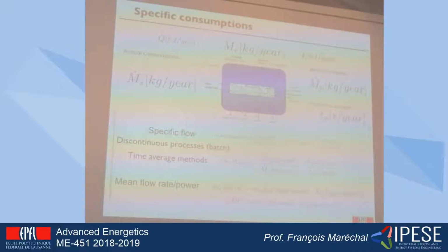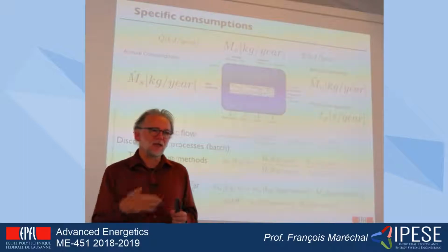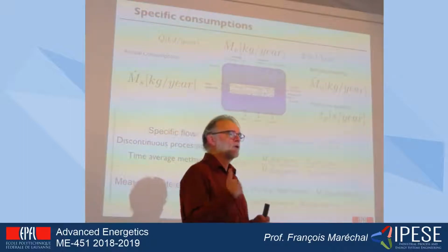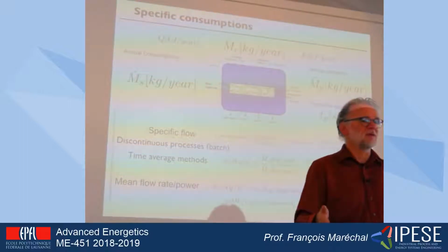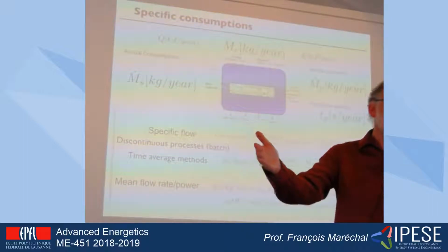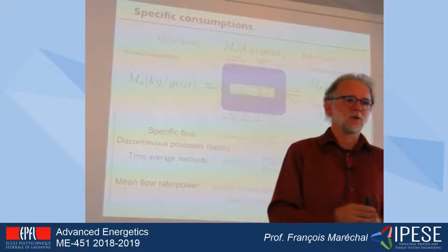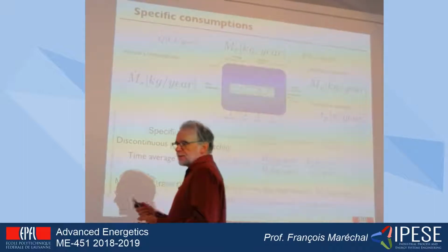Okay, this is a time averaging method that will allow you to know what is the typical amount of energy that is needed at a given time in a mean value. And the mean value, of course, is something which will have to be taken into account when you buy the heat exchangers. Because now, if this mean value has to be supplied in 10 minutes or in 1 hour, of course, the size of the heat exchanger will be different. Okay? So the time average is one trick.